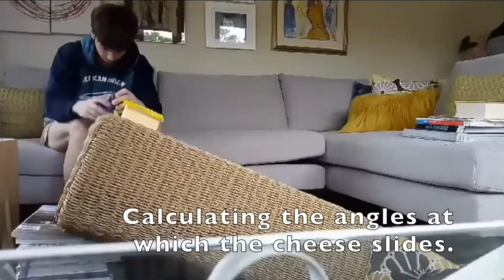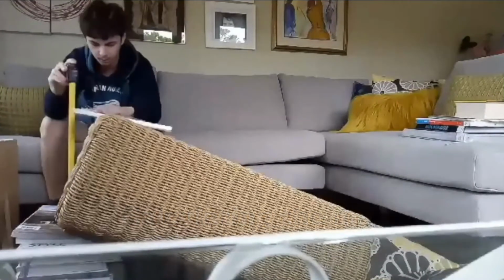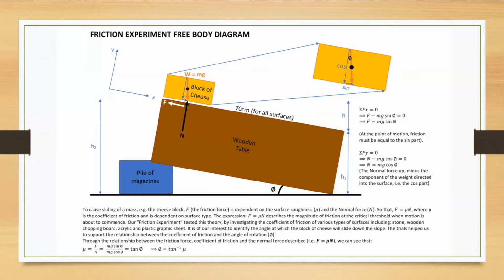We took some measurements and formed a free body diagram in order to obtain the angle just prior to the cheese sliding off. Referring to our free body diagram of the experiment, we must first take a closer look at the weight force of the block of cheese on the right here. The x component of this weight force is equal to the mass multiplied by the acceleration due to gravity multiplied by the sine of the angle. This means that at the point of motion, friction must be equal to the sine part. As for the y component of the weight force, the normal force going up is in fact equal to the cos part here, and that is the component of the weight force that is directed into the surface.